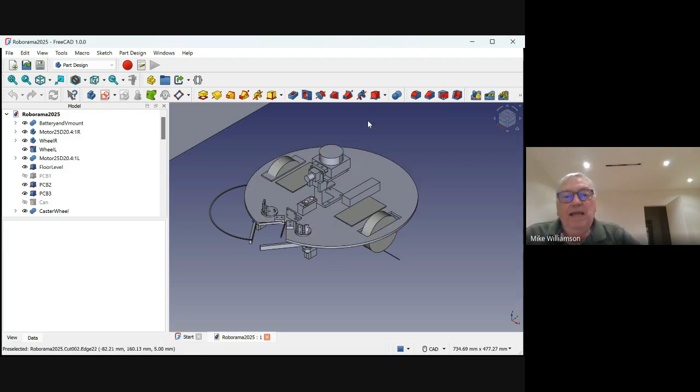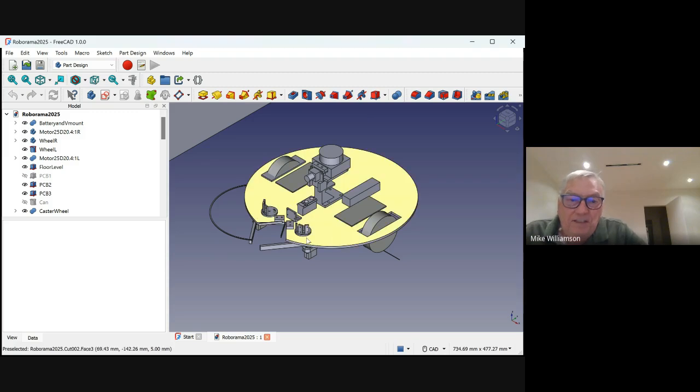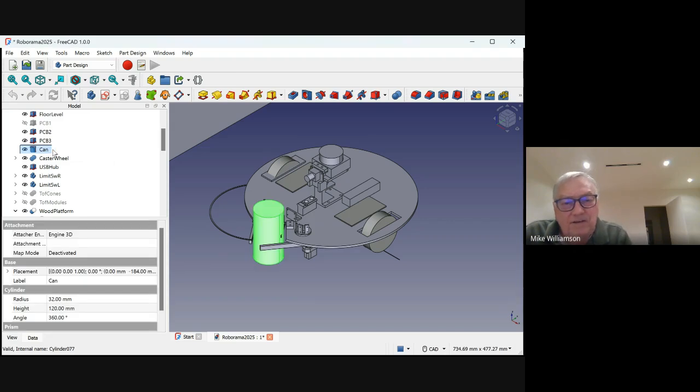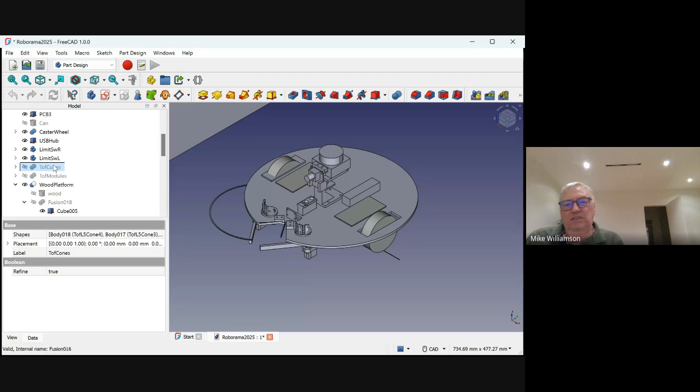I just wanted to get the mechanics, the drive chain, to work. You can see here the limit switches I'm going to put on there, and these operate independently with the servo motor. You can see a servo motor down there, and it'll pull the can in. If I turn the can on, it pulls it. So basically, I have a full size, accurate sizing of everything, so that I know that it's going to grab the can right.